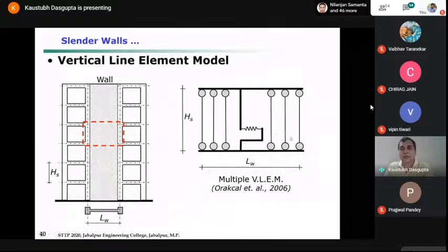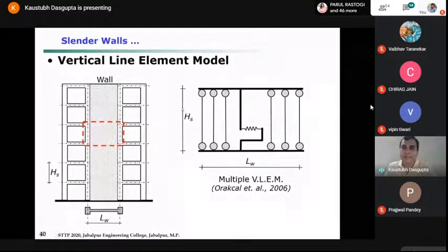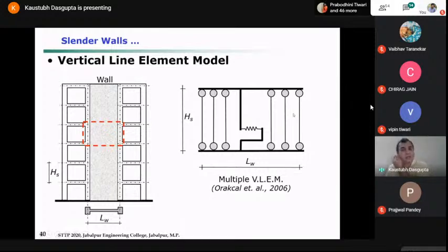Here also they are the truss elements. If this is taking the compression, these become struts, these become ties, and vice versa, whichever way you apply the force. Okay, so these elements, what you are seeing as pinned elements, these take care of the longitudinal forces, bending forces, and the shear part is taken by this spring. Okay, so whenever you apply the shear, this spring should be able to take care of the action.